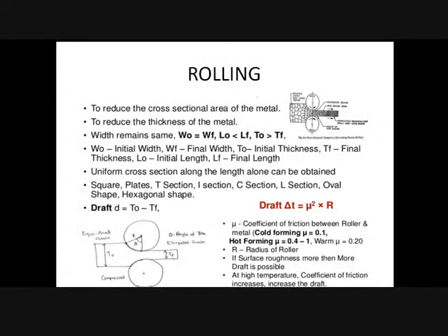To ensure stable equilibrium of the rolling operation, the surface between the roller and strip must be equal at both sides. Look at the diagram in the bottom left corner. The diameters of both rollers must also be equal. Because the diameters are equal, the rpm will also be equal, so the use of a second gearbox is avoided. There are many assumptions made in the analysis of rolling.